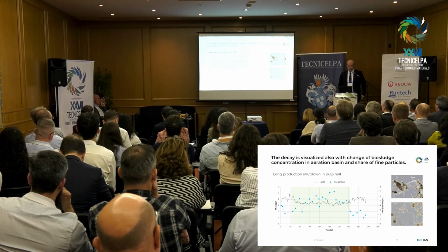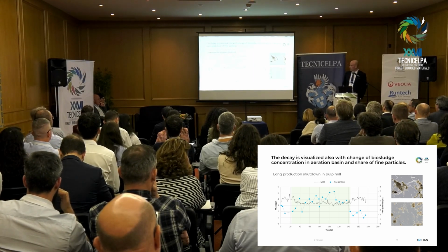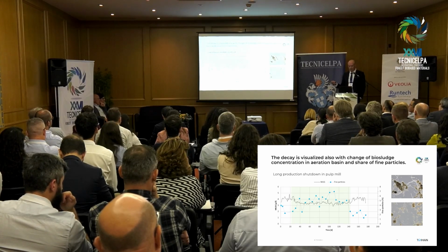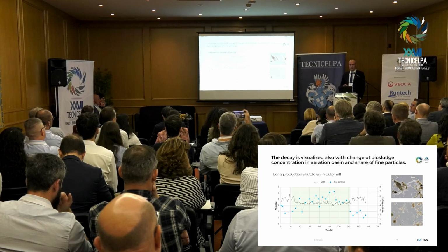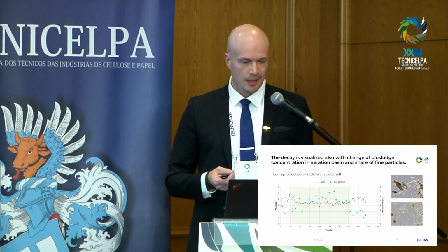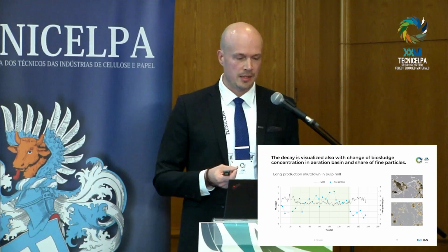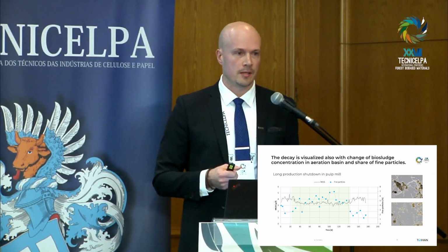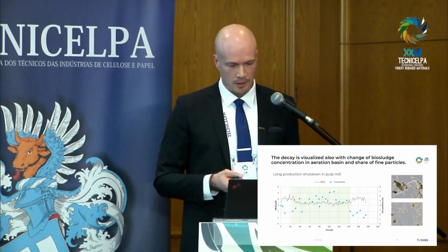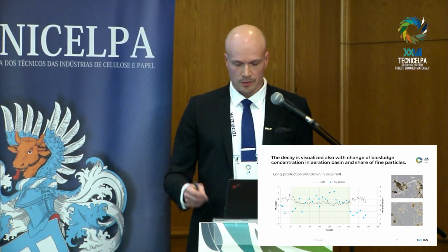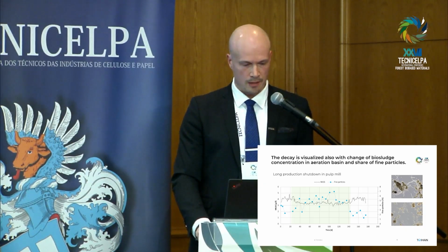And this is with sludge concentration laboratory analysis, mixed liquor suspended solids, so MLSS, referring to sludge concentration in the aeration basin. So when the flocks or biomass decay, it decreases the concentration, which is quite logical, and fine particles appear. So same story again.